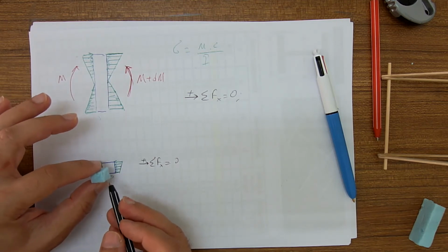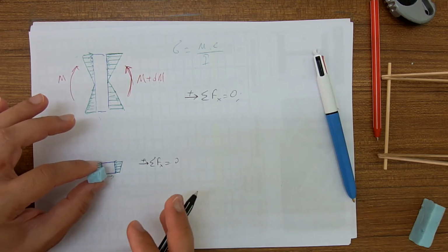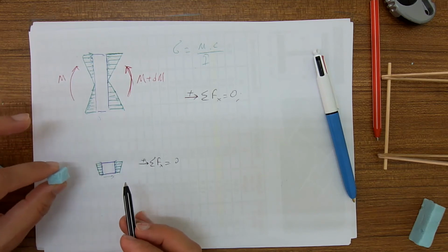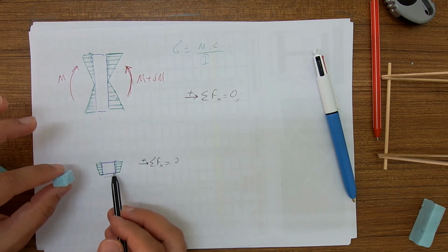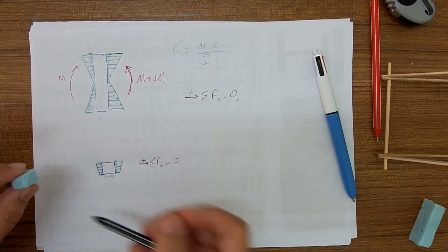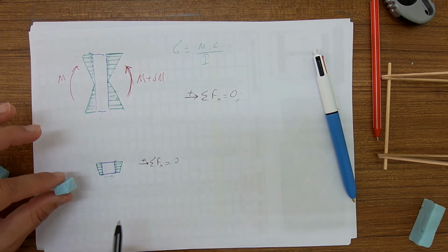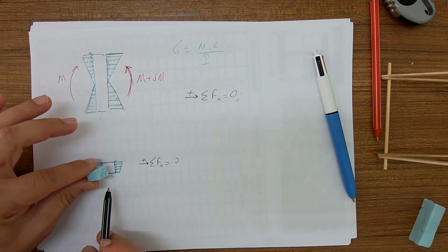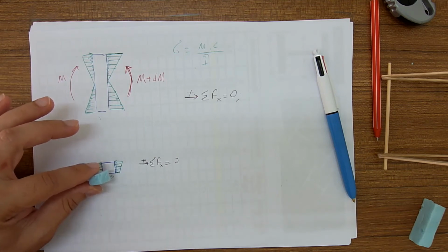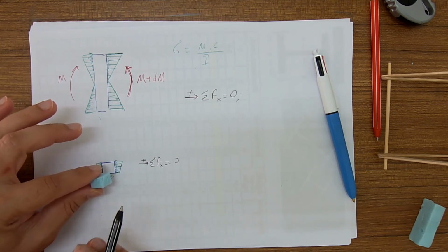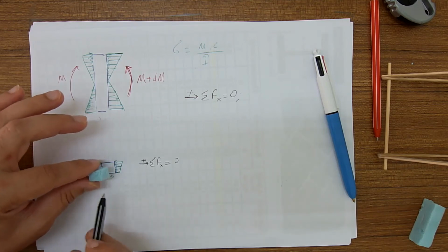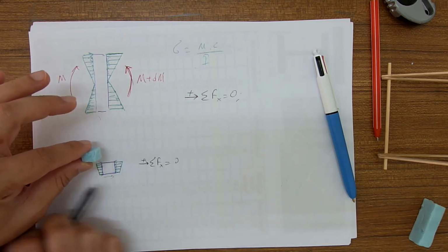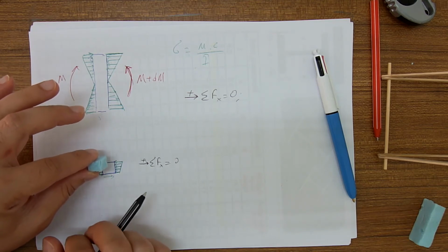Therefore, if we had no other stresses, this little segment would move to the left, because those on the right is larger and they are pushing to the left. So we need something to keep this segment in equilibrium. It is the shear stress that will hold this in static equilibrium. So it has to be in opposite direction. Okay.